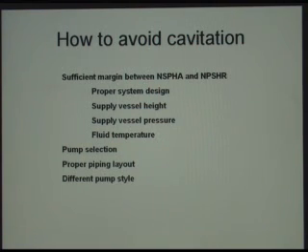Does this happen in all the systems or only in oxygen-rich systems? It can happen in any fluid. We design our systems away from that so it won't happen, but it has the potential to happen everywhere, wherever there's a liquid. It doesn't have to be gas-rich or oxygen-rich because it's not an entrained gas that is forming. If it was water, it's actually steam that's being formed.